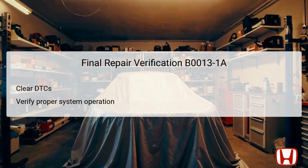After performing the necessary inspections and replacing any faulty components indicated by the troubleshooting steps for DTC B0013-1A, it is essential to verify the repair. Start by using the Honda Diagnostic System, HDS, to clear any stored DTCs. Following this, turn the vehicle back to the on mode and check for the illumination of the airbag warning light and the presence of any new DTCs.